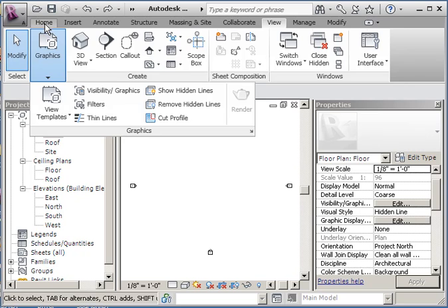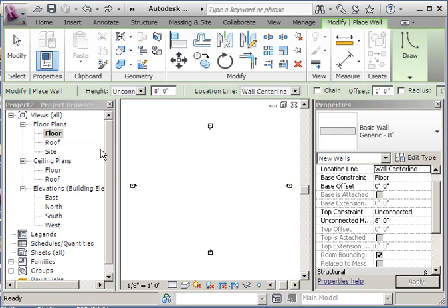So it says go find the wall tool, and once you find the wall tool, it says select the wall tool and click on the chain in the options bar. So we want to click on chain, and then it says click once at the beginning point, and then you're just going to wrap yourself a rectangle around. This is an easy way to do it. I like the rectangle tool better because it's easier to get one rectangle, but this would be easier for multiple shapes of walls.